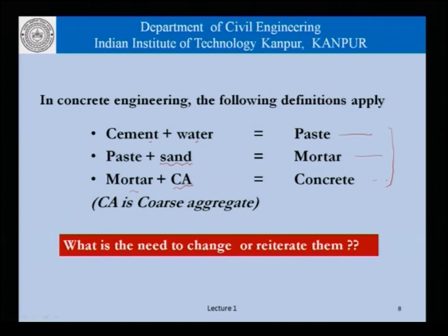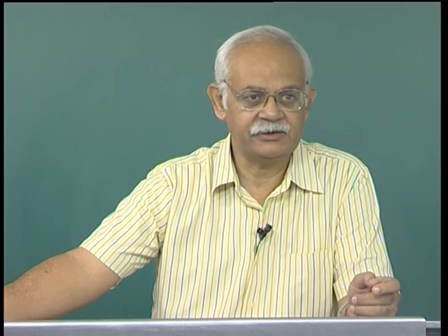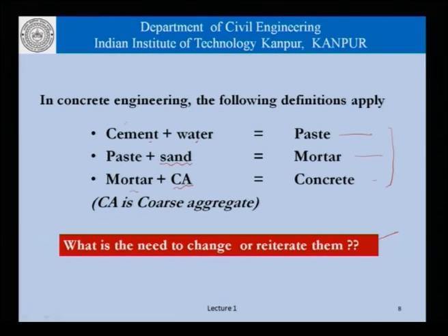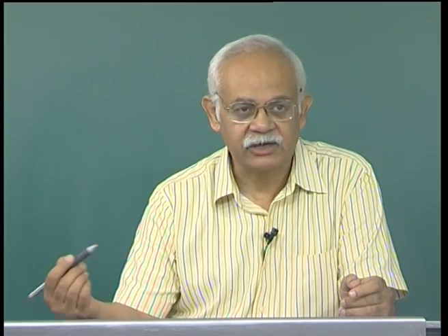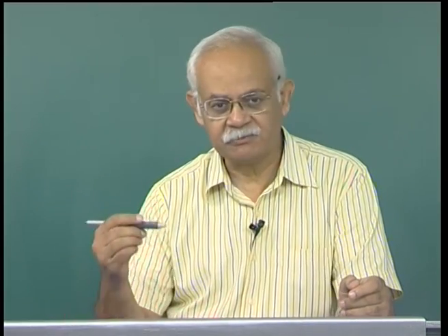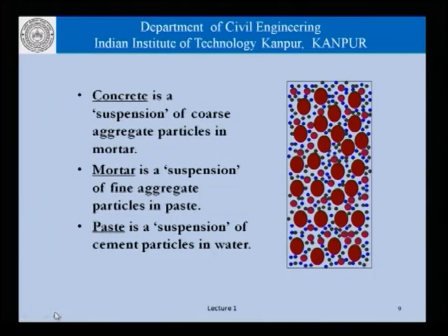This is largely understood. However, what is the need to change or reiterate this at this point in time? The idea basically is that once we understand this, then when we add special materials or new materials to this old combination of cement, water, sand and coarse aggregate, then we have to understand or we have to decide whether it will be counted towards the paste volume or the mortar volume or the coarse aggregate volume and so on. So keep this in mind as we go along in these lectures.